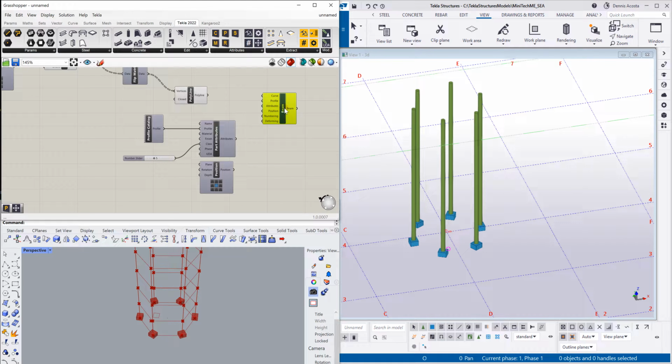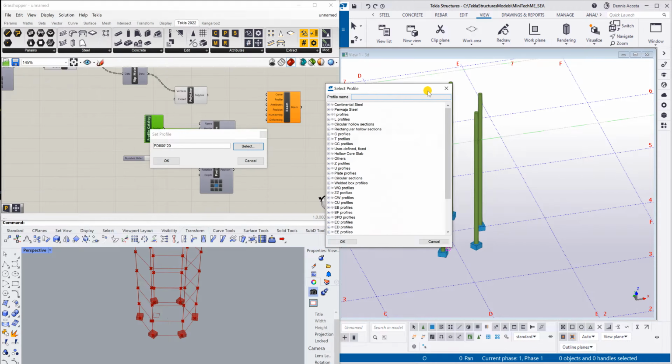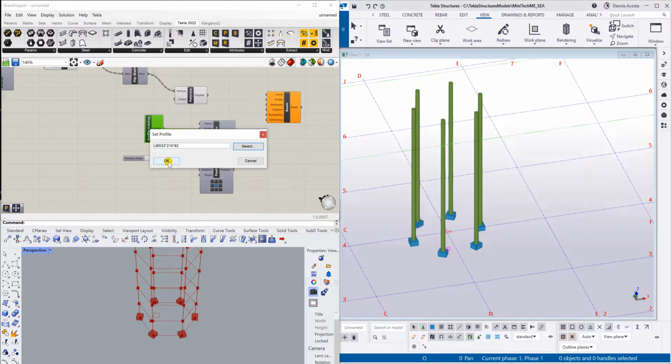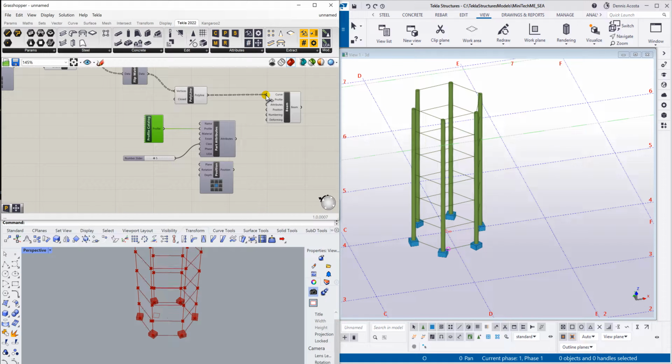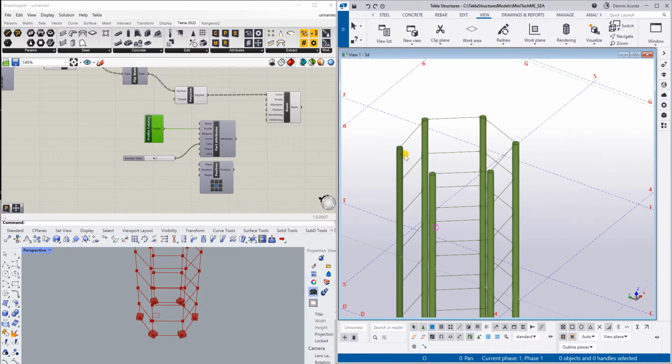Now, before I link this one to this curve, I'm going to change the profile catalog first. So let's say the profile catalog, I can just simply select any beam size here. Let's say the I section, or you can choose whatever section you like. Let's say I use the UB section, UB maybe 533 by 210. Okay, and let's say click here, and now select the polyline here. All right, okay, polyline. But if you notice here, the polyline is not closed. So we're going to close that one later, but let's show first the attributes here.